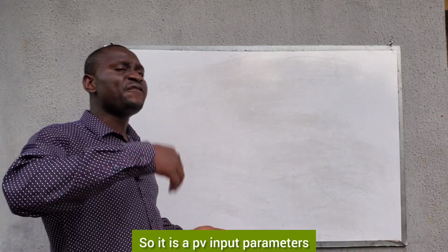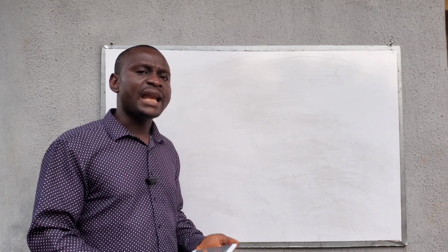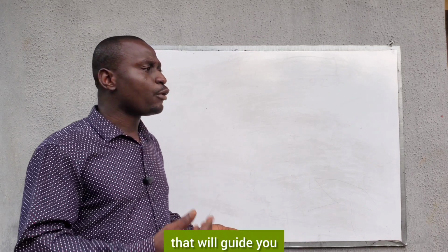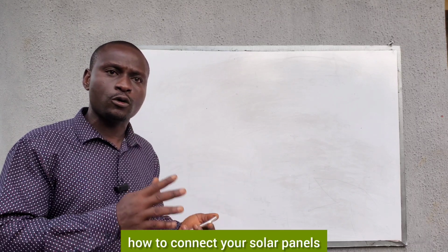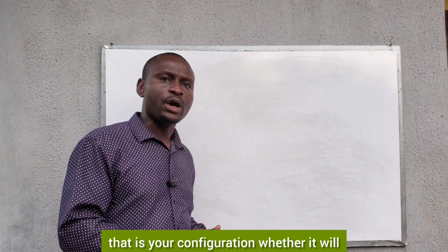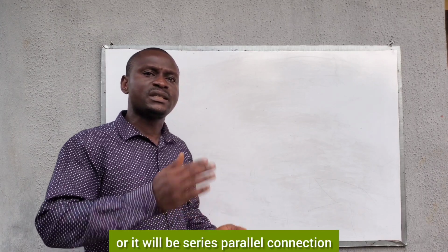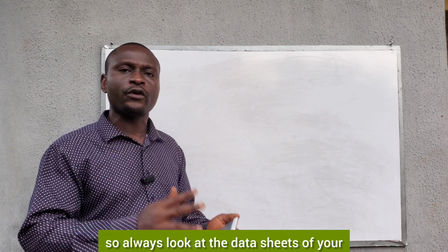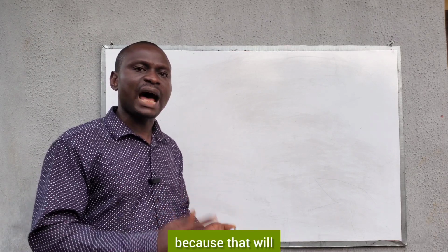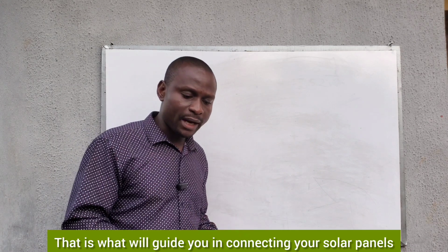It is the PV input parameters, that is the PV input voltage and the PV input current, that will guide you on how to connect your solar panels. That is your configuration, whether it will be parallel, series, or series-parallel connection. So always look at the data sheet of your solar charge controller, because that is what will guide you in connecting your solar panels.